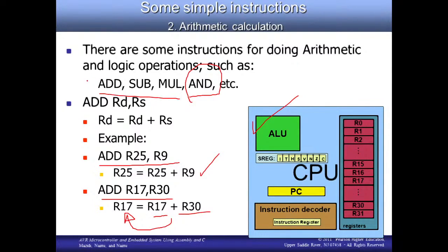These are all assembly language instructions, and it's very easy for a human being to understand them. But as I told you, it is very difficult for a computer to understand this. So we require AVR Studio, which uses an assembler. It will assemble these instructions and produce a hex code out of it, and that the machine can understand. Hex code is basically a sequence of binary ones and zeros, and our microcontroller and processor can understand ones and zeros. It cannot understand the assembly code directly.